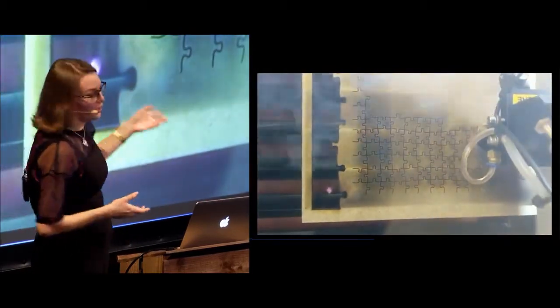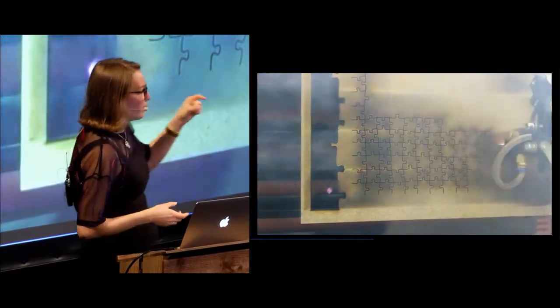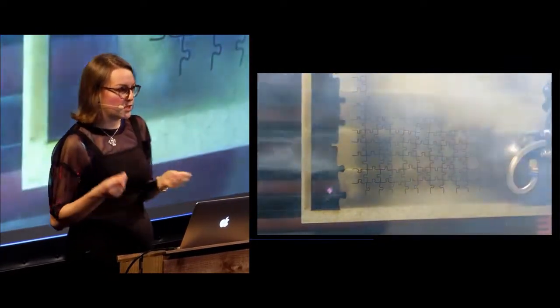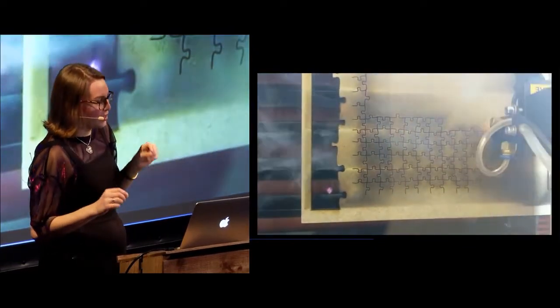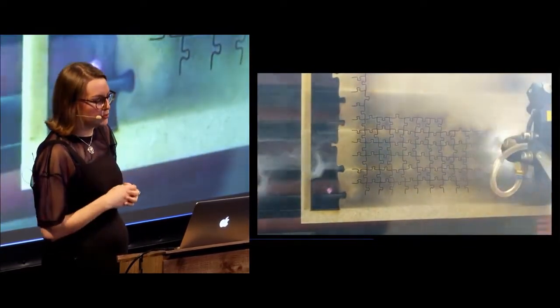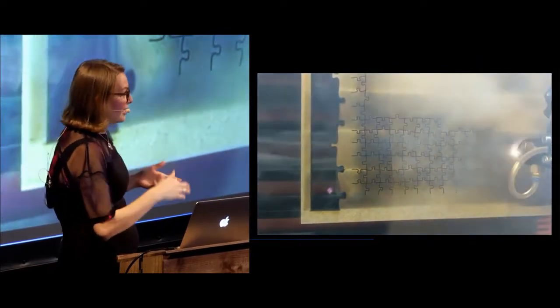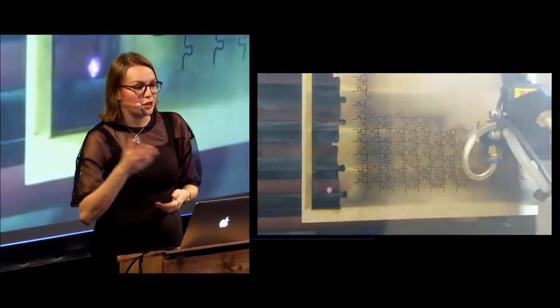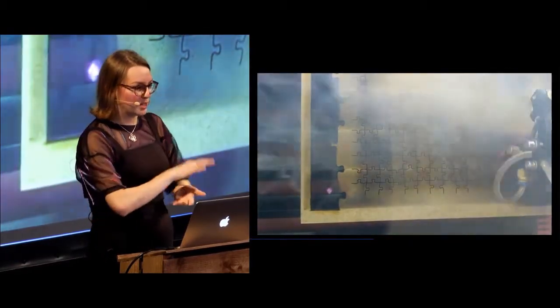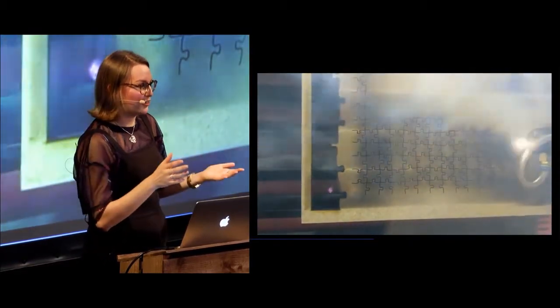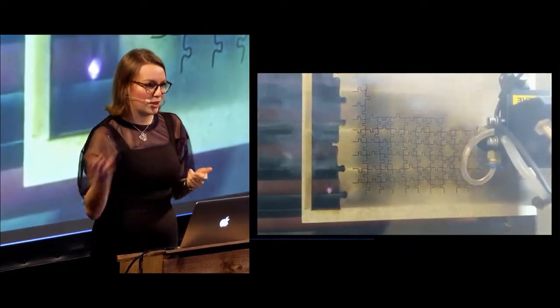Like with this, I wanted to use 6mm MDF, which is medium density fiberboard. It's like a wood composite material. That's because it's a very consistent material, and 6mm is nice and chunky for a puzzle. But it's hard to burn through that density of wood without it getting really smoky. Usually you wouldn't have to worry about that, but with this, in theory, I have a picture of a puzzle printed on it already, so you need to care about the smoke because that might affect the puzzle.